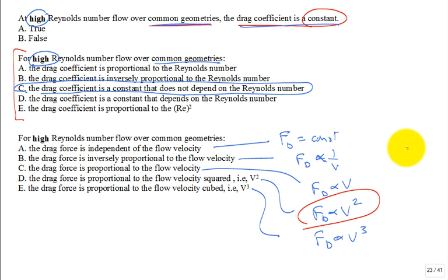Now there's one other thing: what is the power required to keep a system pushing through the fluid? If I have an automobile and the engine dies, will I still go 60 miles an hour down the road till I hit Houston? No. What's going to happen? The friction drag, all that. But if you just think aerodynamic drag, forget about the bearings and the rolling resistance, you have to overcome that to drive at constant speed.